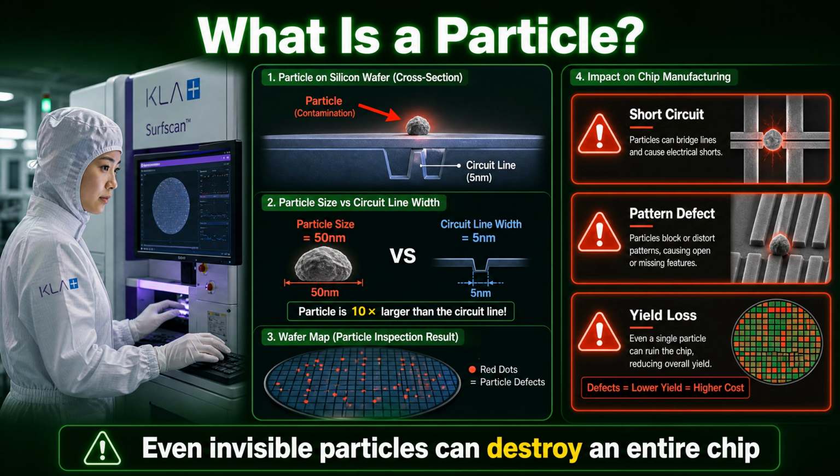A particle is any microscopic foreign material present on the wafer surface. As circuit line widths shrink to just a few nanometers, even a particle that is invisible to the naked eye can be larger than the circuit itself. When a particle lands on a circuit, it can cause a short circuit, a pattern defect, or complete yield loss.